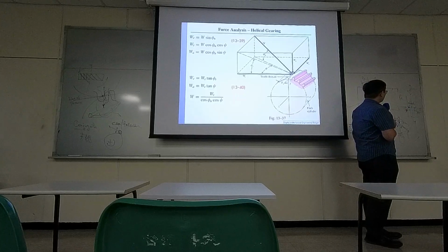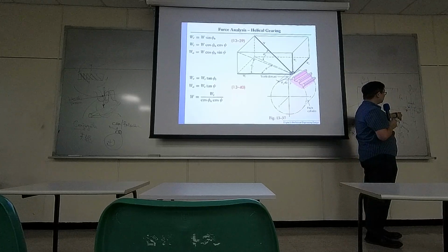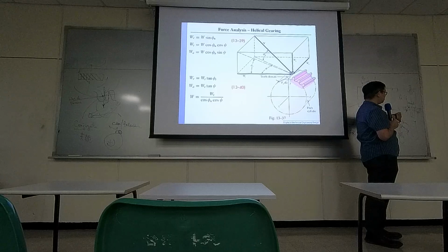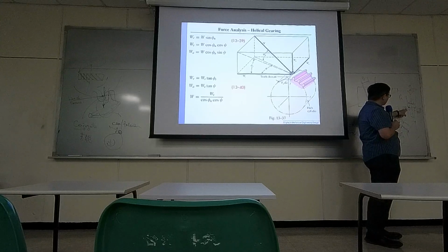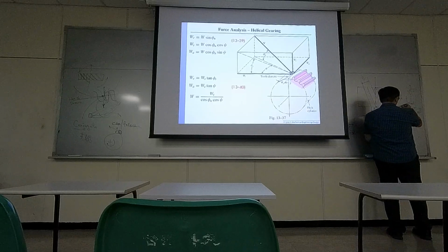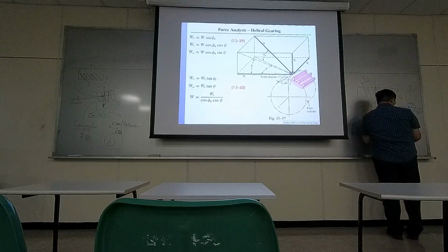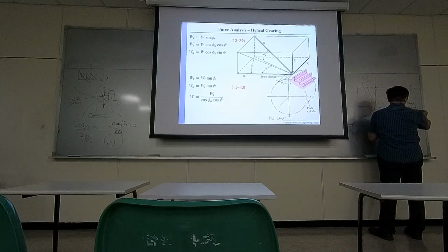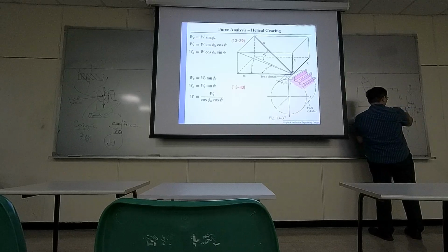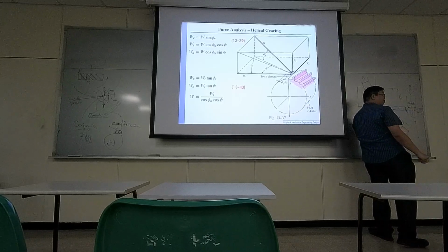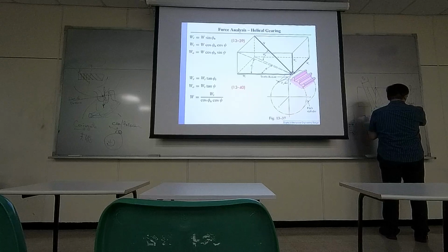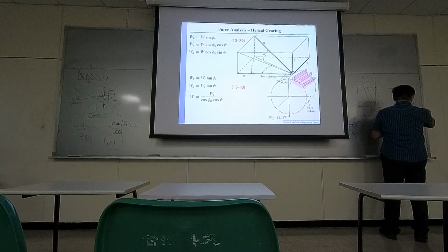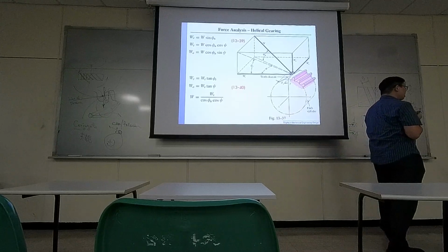Okay? So you may need to worry about, is my geometry right here strong enough? Maybe the bottom is a base plate. Okay? So it's like a plate. Is the plate thick enough? Will the stress concentration right here affect the geometry?